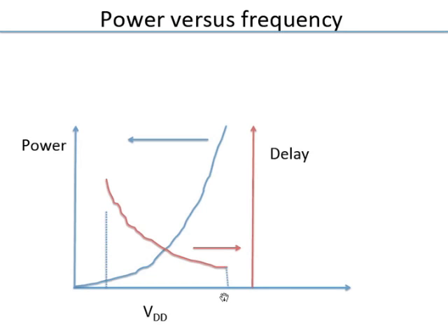And of course, there is a certain maximum voltage which you can use for your chip. That maximum voltage is basically determined by what voltage will break down the transistor. The transistor has very small geometries, right? The oxide thickness is very small and so on. So the electric field is basically the voltage divided by the distance. When you have very large electric fields, it can pull out charges and essentially damage the device. So that determines VDD max, which is usually about a volt, 1.2 volts in modern processes.